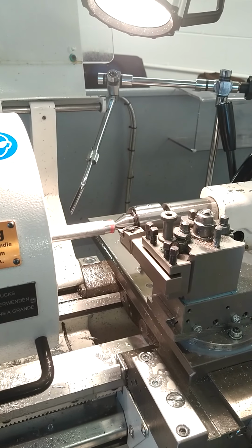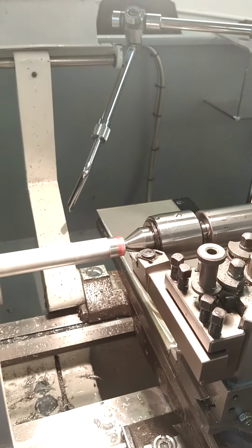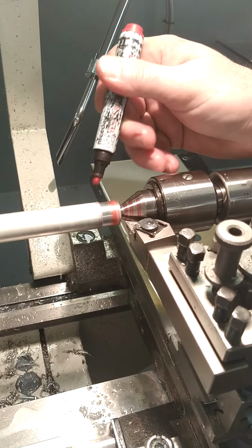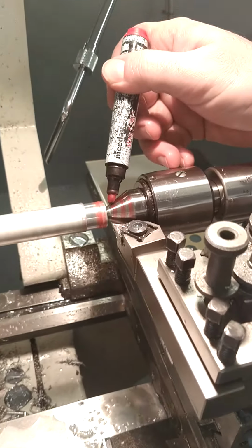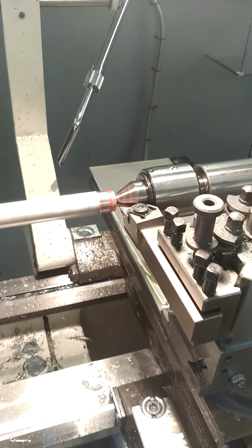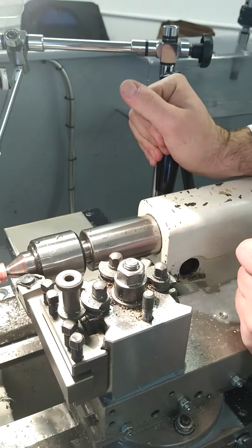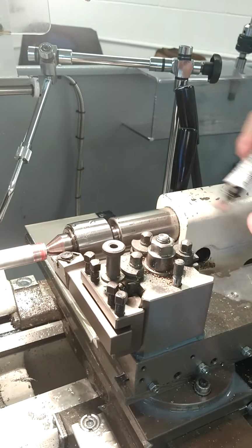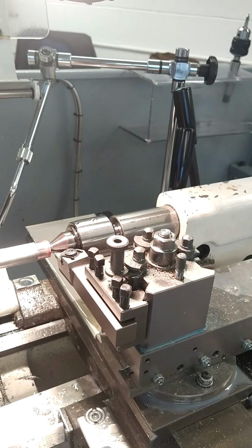But now what you want to see when you turn on the machine is you want to ensure that the revolving center is rotating with the work, and that it's not like this, it's not rotating. If it's not rotating, then it's not supporting the work, therefore it's going to be oscillating up and down. So ensure that it's fully engaged, and when it's fully engaged, then you apply on your quill lock to support the revolving center, keeping it a lot steadier. That's in that instance.